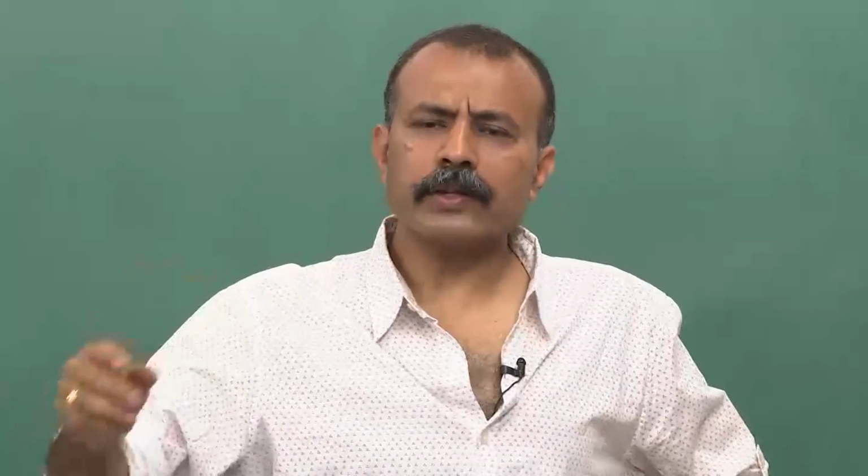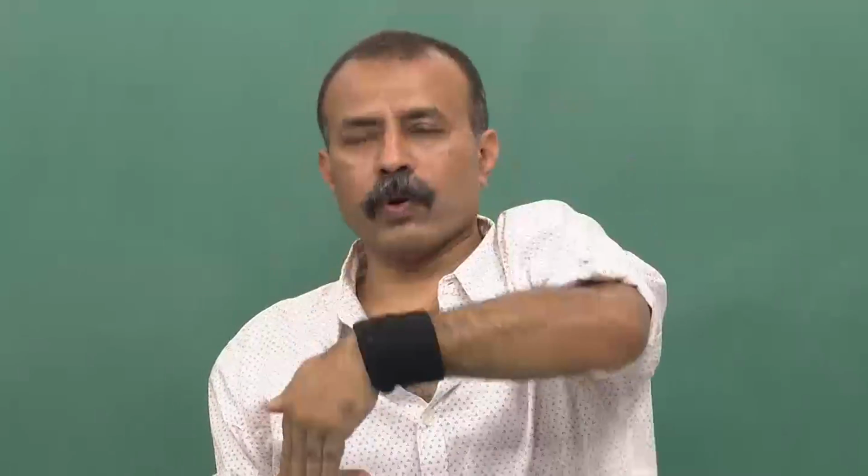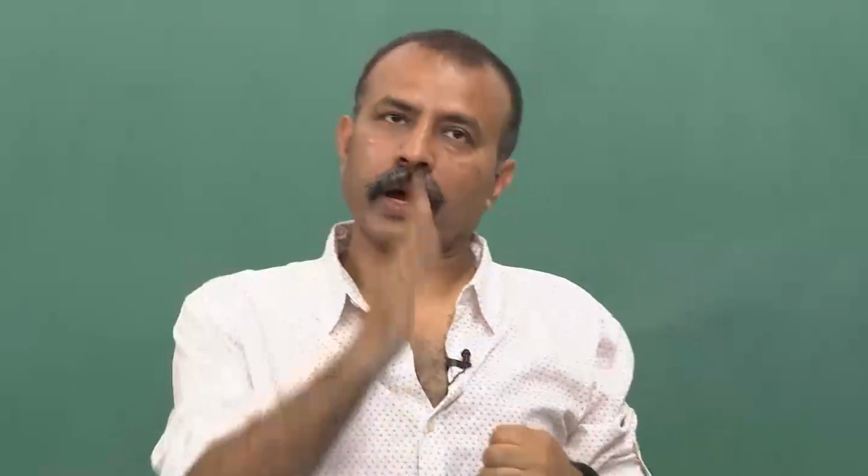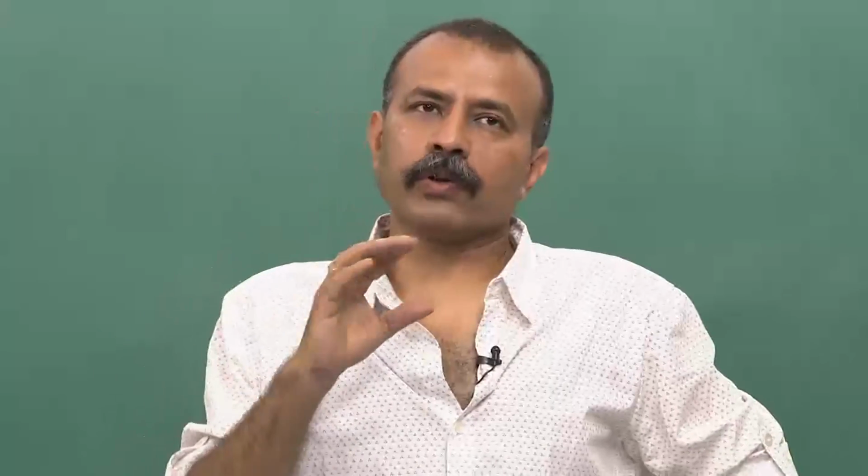So, let us summarize. We talked about air moving from the bottom going up, the updraft. We talked about air moving from up going down, the downdraft. And you have the cross flow like this. Air is coming in and hot gas is going out, and they are at the same level. So, these are the three classic fundamental fixed bed gasifiers that you needed to know.